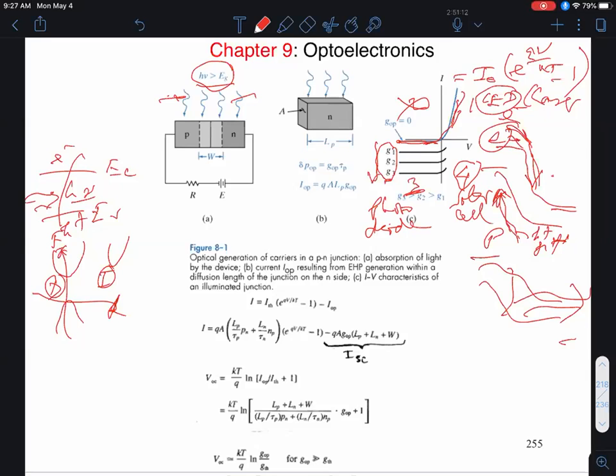All right, so let's determine the basic equation for such a photodiode. Okay, so what I have over here is my diode IV initially without any light. Okay, so that's my regular diode IV. Some reverse saturation current, e to the power QV over KT minus 1. But now, if I shine light, I get an extra photogenerated current component, which I call I optical. Okay, so that's these extra electron hole pairs that are being created, and that results in an extra optical current.